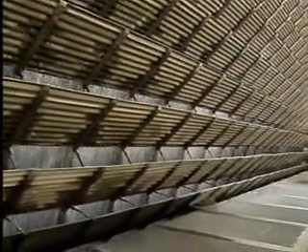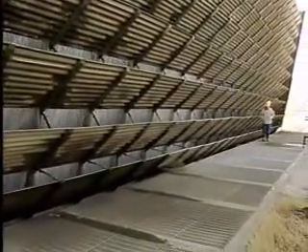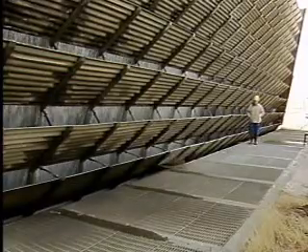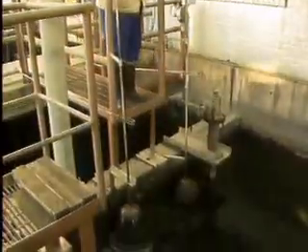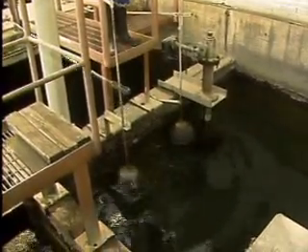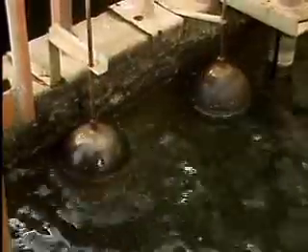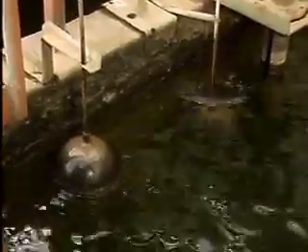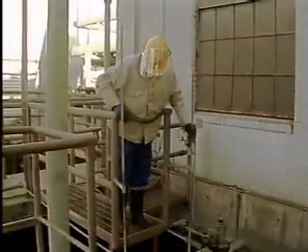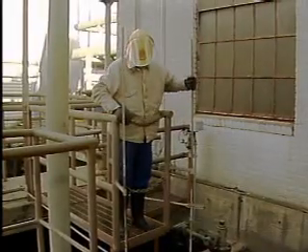One thing to check is the water level in the catch basin. If the level is too low, the circulating pump could lose suction. That could damage the pump and reduce or stop the flow of circulating water. The level in the catch basin is sensed by floats in the basin. Operators should check the floats to make sure they move freely so that the proper level can be maintained in the basin.